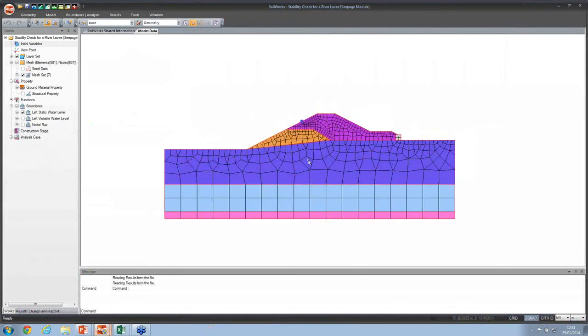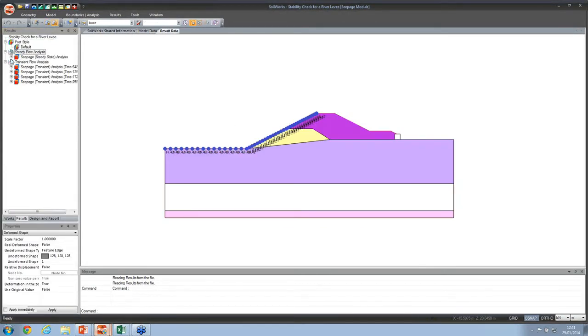So you can see an embankment here, and in a similar fashion you can define, so this is more like a commercial problem. You can define the pressure head values here, total head values, and you can define the boundary conditions here where you want to obtain the phreatic surfaces. And once the problem is analyzed, you can check the results.